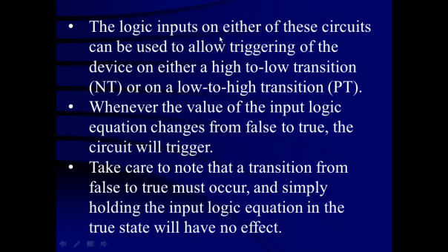The logic inputs on either of the circuits can be used to allow triggering of the device on either a high to low transition, which is called a negative transition, negative edge trigger, or on a low to high transition, that is a positive trigger, or positive transition.